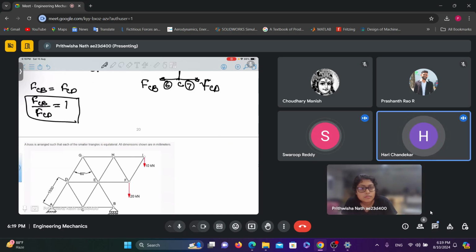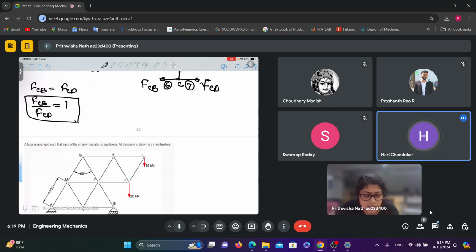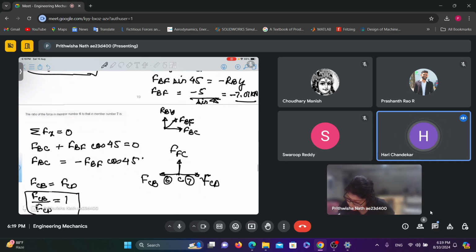Ma'am, I had a doubt about member 6 and 7. Yes. We have found the ratio to be 1. Now, just the nature, whether it is tension or compression, we just had to discuss that. As per this, member 6 is in tension, correct?